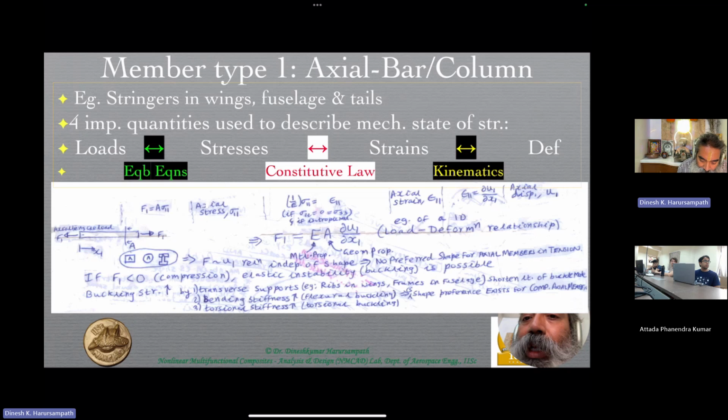So if you want to increase that buckling strength and therefore delay the buckling or even completely avoid it, there are multiple ways to do that, because the quantities that it depends on are E, I, and L squared. And I, the moment of inertia, can be improved by going to an appropriate shape. We saw that as far as this equation is concerned, it depends only on the size, namely the area of cross section A. But once I comes into the picture because of the possibility of buckling, then you have a preference for the shape also. It's not just the size, that is how much area of cross section you have, but how you redistribute that within the cross section. So that becomes critical as well.